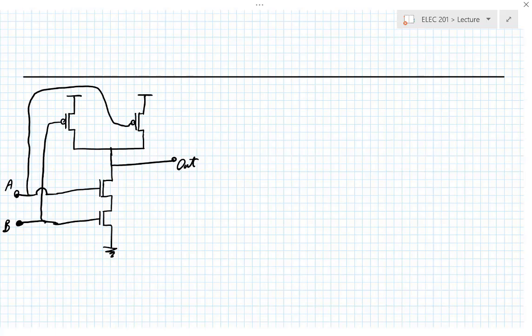So the point is, that's a very abstract way of looking at it. But in reality, these are transistors made out of flesh and blood, or those wires and pieces of material that you saw in the electron microscope. And these zeros and ones are voltage signals. So you would apply maybe 2 volts here, and you would expect here to go between 0 and 2. And to be able to fully understand the circuit and make sure that it works properly, you have to basically go through a full analysis of finding out what each voltage is everywhere in the circuit and what each current is flowing through every branch of the circuit. Okay?